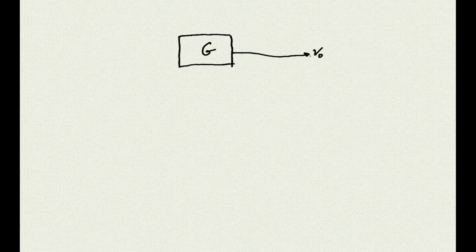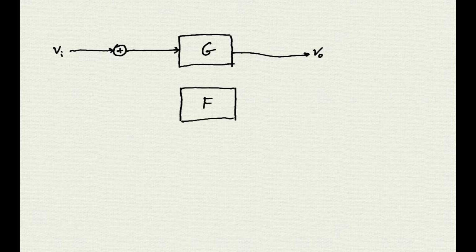To talk about active filters, we need to begin with the concept of amplifier with negative feedback. Such an amplifier is made of a module with gain G, which provides directly the output based on its input. The input of the amplifier is given by the difference of the signal coming into the device minus the output of the device itself, adjusted by a certain factor F.